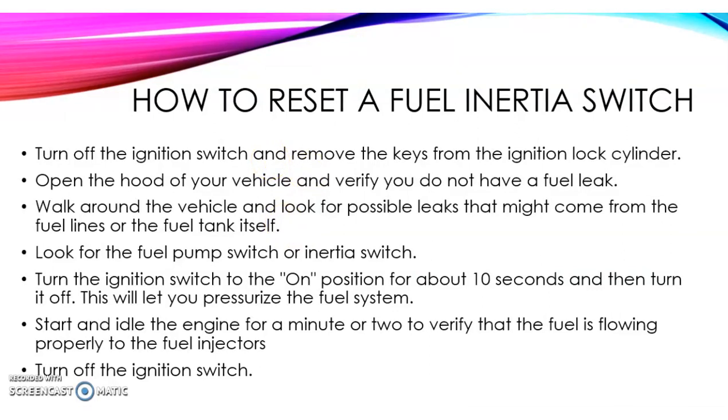Okay, so that's how to reset the fuel inertial switch. First, turn off the ignition switch and remove the keys from the ignition lock cylinder. Next, open the hood of your vehicle and verify you do not have a fuel leak. Walk around the vehicle and look for possible leaks that might come from the fuel lines or the fuel tank itself.